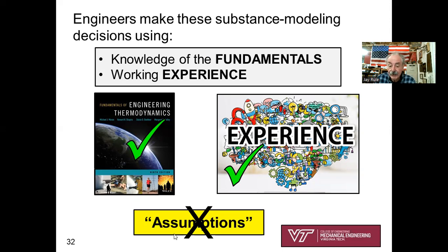And so I'm not a fan of the word assumptions. Assume that, because really it's up to the engineer to model the substance, not just assume it's an ideal gas. Okay, so do you get the idea that you could be given a steam turbine problem and write down, assume it's an ideal gas? Well, you'd be way off. That is not a good engineering model for steam vapor under most conditions. So anyway, I'm not a big fan of that word assumptions. Big fan of you getting the fundamentals and then gaining experience to make these modeling decisions.